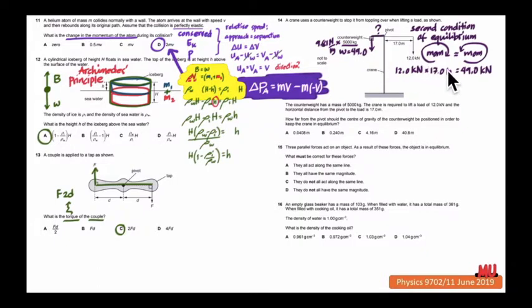Alright, now for the moment, counterclockwise is this force multiplied by the distance. Let's call this distance x. The unit kilonewton then can be removed. Alright, and this figure 49.0 to be placed here at the other side. The x therefore is the result of our calculations here, which is 4.16 meters, the option C.